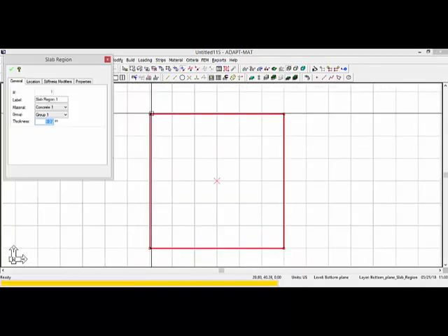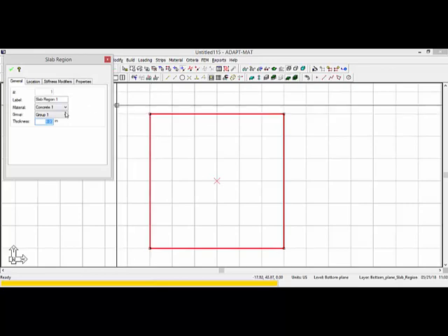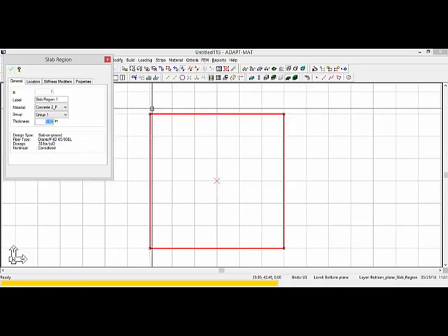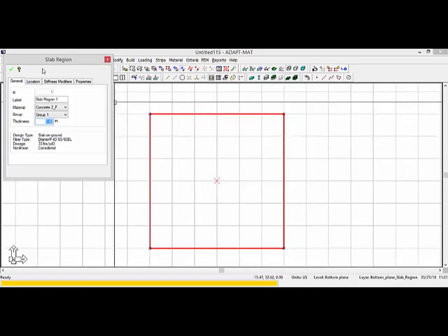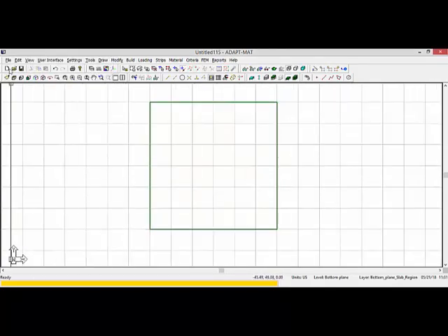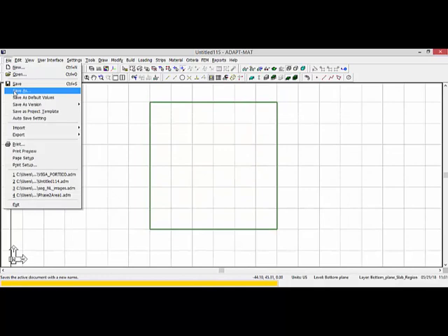I'm going to go ahead and double click on the panel to open the property menu, and we'll set the thickness to 5.5 inches, and I'm going to set the material to this concrete 2F. This is the fiber material, and it shows me right here what that material is. This is a slab on ground. The fiber type is shown as Dramix 4D 65, etc. The dosage is 33 pounds per cubic yard, and we're considering nonlinear analysis for the design of this slab panel. I'll select the green checkbox to close the panel, and now I'm going to save the model.